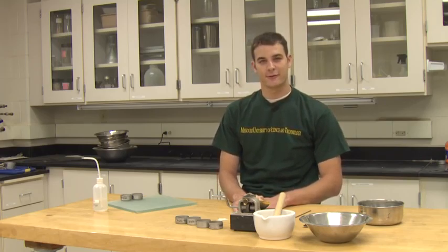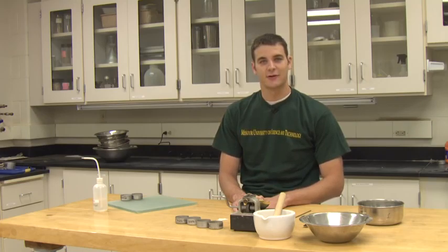Today we will be going over the laboratory procedures on performing Atterberg limit tests. These tests include the liquid limit and the plastic limit tests. They are used to classify the fine-grained portion of a soil. The practical application of Atterberg limits in geotechnical engineering includes soil description, quantitative soil classification, and correlations to engineering properties